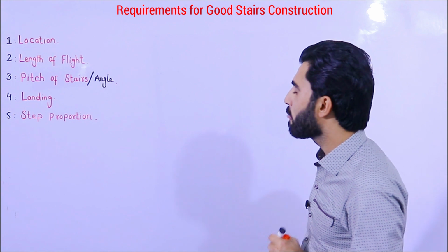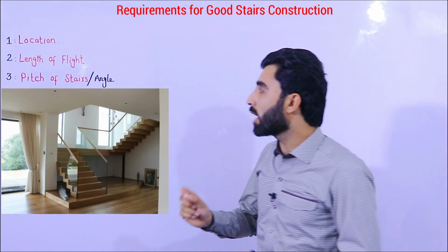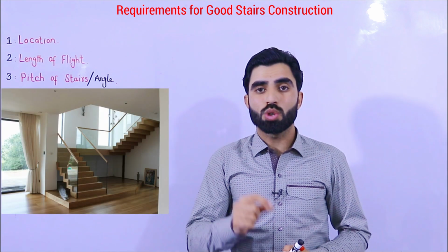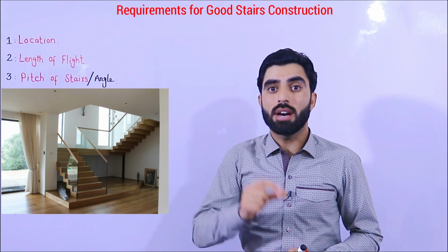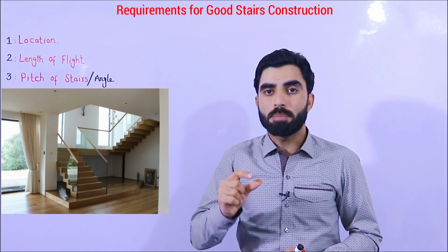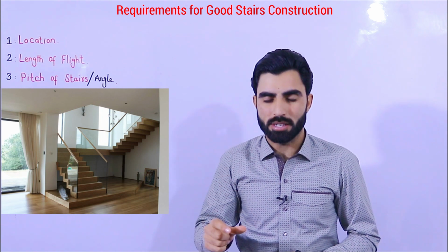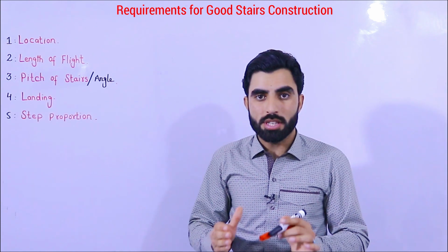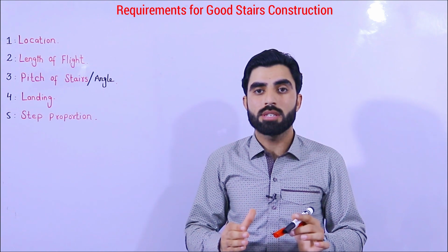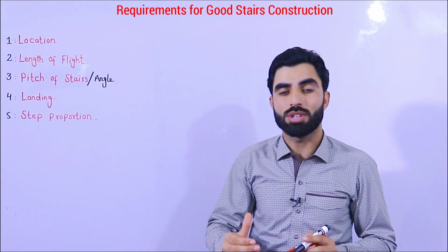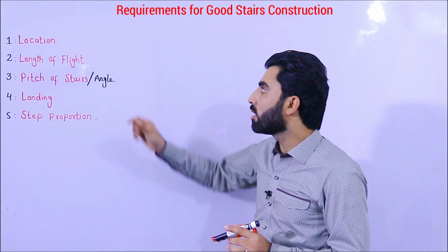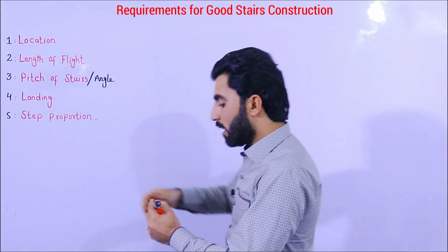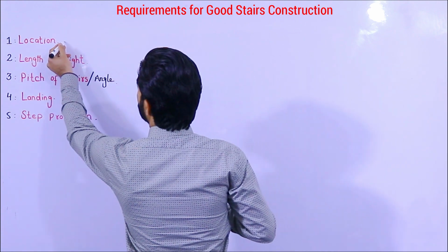Good staircase. The first one is location. Remember guys, the staircase should be located in order to obtain proper ventilation and lighting. And the stair should also be easy to access for all rooms. So these are the requirements in location.